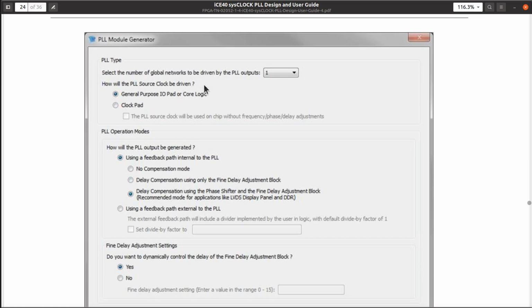Okay. Today we're going to focus mostly on core because of the mistake I made when I built my board. I connected it up, and my oscillator is not connected to a pin, a pad that can be directly connected to the PLL. All right, so what I do is, you'll see in a minute, the free running clock frequency goes into the FPGA, and then I simply route it through the FPGA and then into the PLL, and I configure the PLL with a core input.